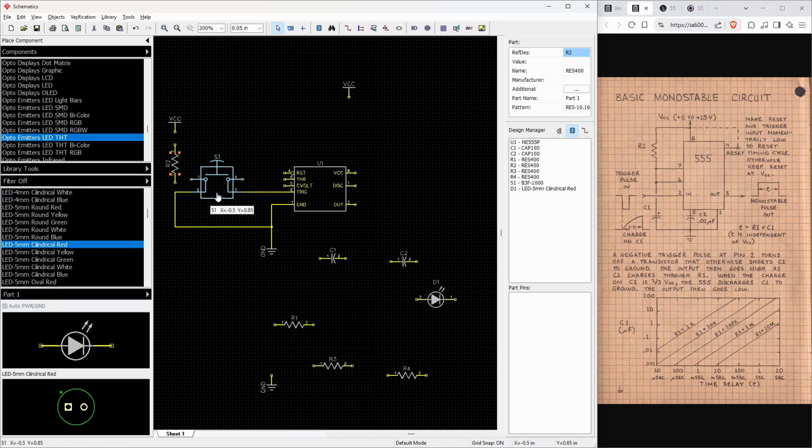So if you've ever done anything with an Arduino, you know that when we have a switch like this, it's fine to have it go to ground when you push the button, but what is it when you're not pushing the button? It's hard to say, it's just floating. There's nothing here to say that it's actually high when it's not being low, right? So we want to make sure it has some connection when it's not going to ground. So what we're going to do is use a pull-up resistor, and I will put that right here.